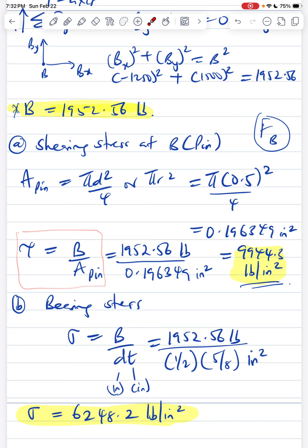That's what shearing stress is, sort of, the easiest example I can give. Then bearing stress is a compressive contact stress between two mating surfaces. That's why for bearing stress, when you're applying force at the contact, we need to account for the thickness.